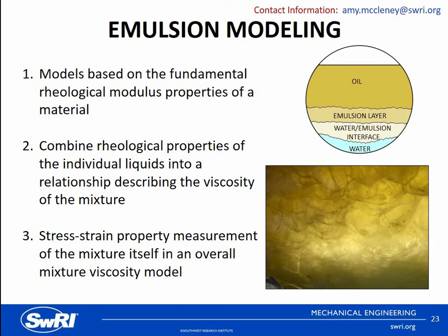So subsequent investigations to what I showed you during this presentation explored more of the emulsion modeling approaches, since we noticed that the solver struggled a bit with cases that had more emulsion present during the experimental testing. An emulsion is a mixture of two immiscible fluids, where one fluid is dispersed in the form of droplets in the other continuous phase.